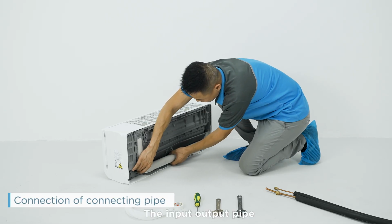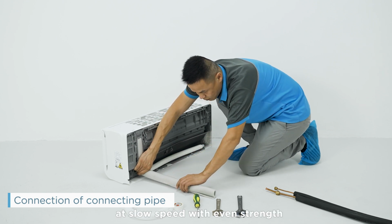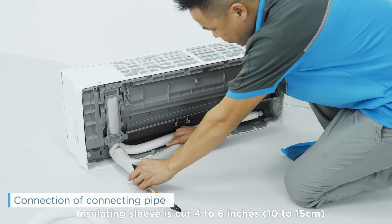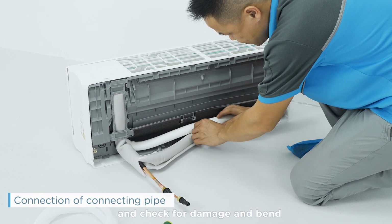The input-output pipe should be adjusted to appropriate position at slow speed with even strength. Insulating sleeve is cut 4 to 6 inches (10 to 15 centimeters) to facilitate the connection with copper pipe and check for damage and bend.